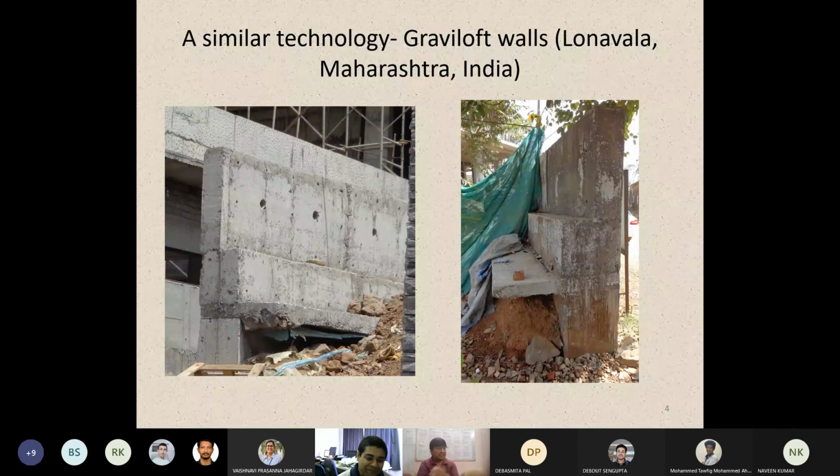Even very recently, what happened is interesting to note. Because this is on the recording, I cannot name it. It was a truss-based structure, where over the truss we use nut and bolt in order to tighten the truss with the members. In that nut and bolt there is a washer, which will not let water as well as air pass. They didn't use this washer. Due to heavy wind, air got introduced into this hall, and the false ceiling and many other things were damaged. So workmanship is always involved.